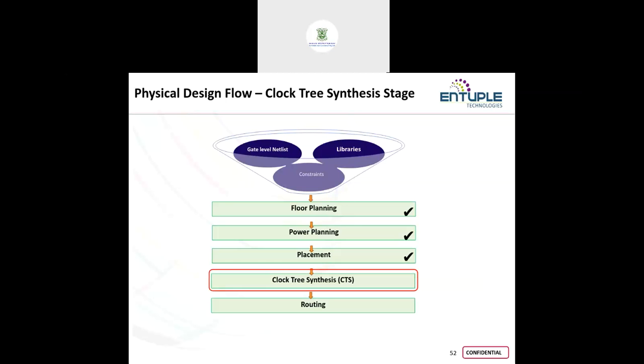See, the GDS file is a binary file format. It is a machine readable format, so that will be taken further for fabrication. When we send a chip to fabricate, we take the GDS file. That is a machine readable file, whatever layout they have will be written in machine language, and that will be further taken for the fabrication process.